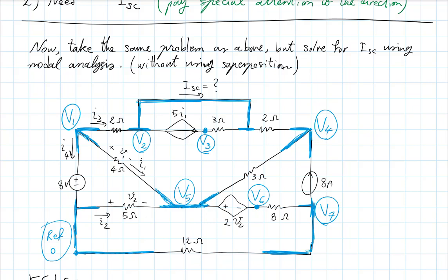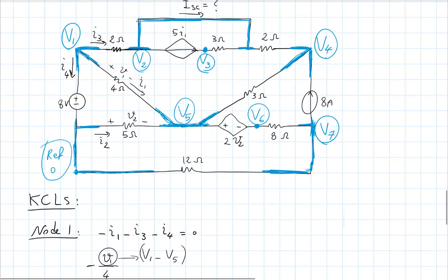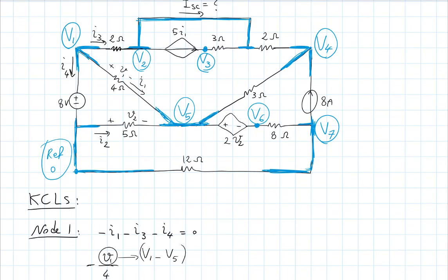So this simple V equals Ri would require that the top left be positive polarity and the bottom right be negative polarity for that 4 ohm resistor. And so I could directly, with experience, just say directly V1 minus V5 divided by 4. And that's really basically it. That's kind of doing a couple of steps in one go that makes things a lot faster.